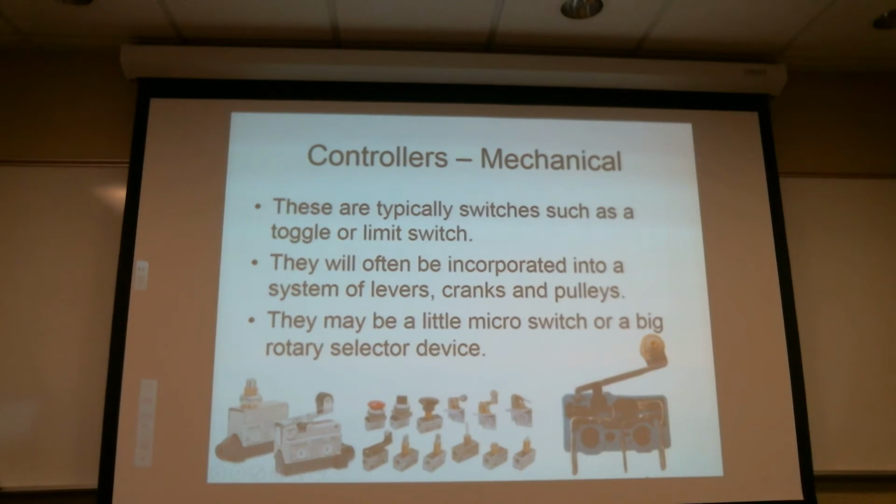They can be connected in all kinds of different ways. I was just helping a friend of mine lay out the torque rod that goes through the length of the airplane from the rear cockpit to the front cockpit to the magneto switch, so that you can operate the magneto switch from both cockpits. It's just a big long torque rod with a couple of levers that are then coupled to the magneto switch, but then off, left, right, both, and then start as a separate switch.